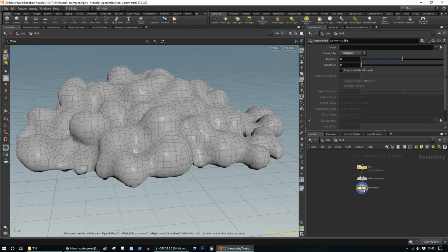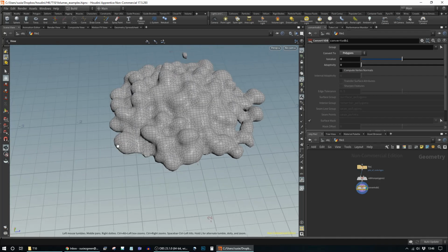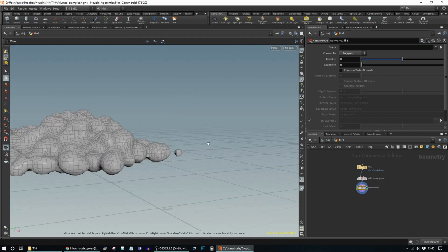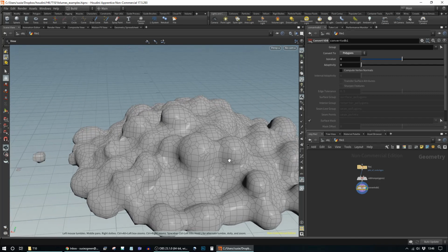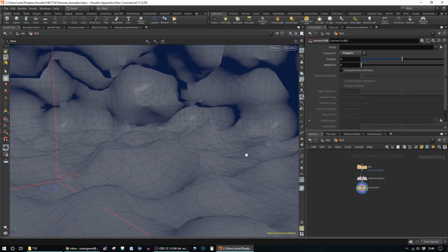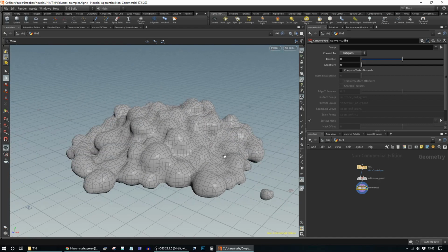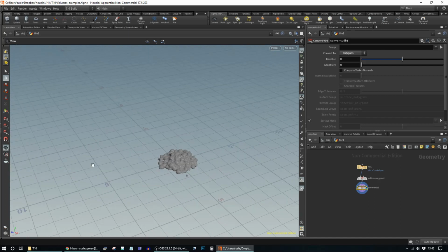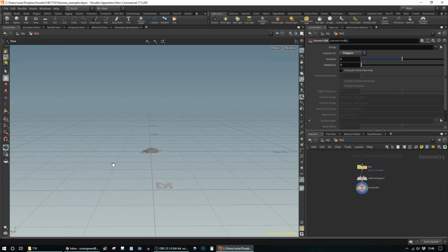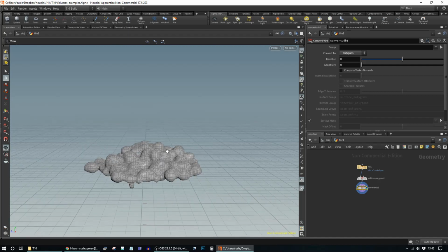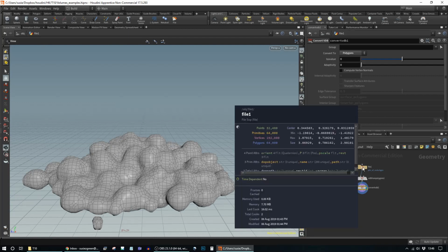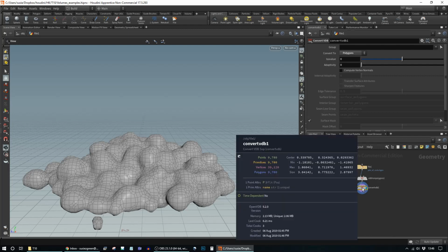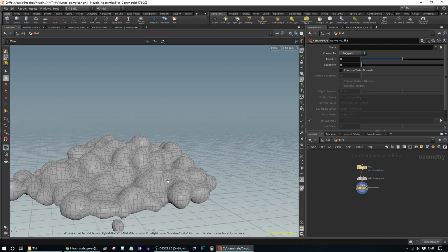So we're taking our VDB that we created and converting it back again to polygons, and you can see immediately that it looks very different because the density of the voxels was quite small. It's munged them all together and we're just draping over the surface of that, and you'll see it's actually hollow inside. Now this doesn't look great, but once you get to about here it starts looking not that different from your original surface, and let's have a look at the difference in size. So the original file is 32,000 polygons and this one is 9,000, so it's a lot more optimal.